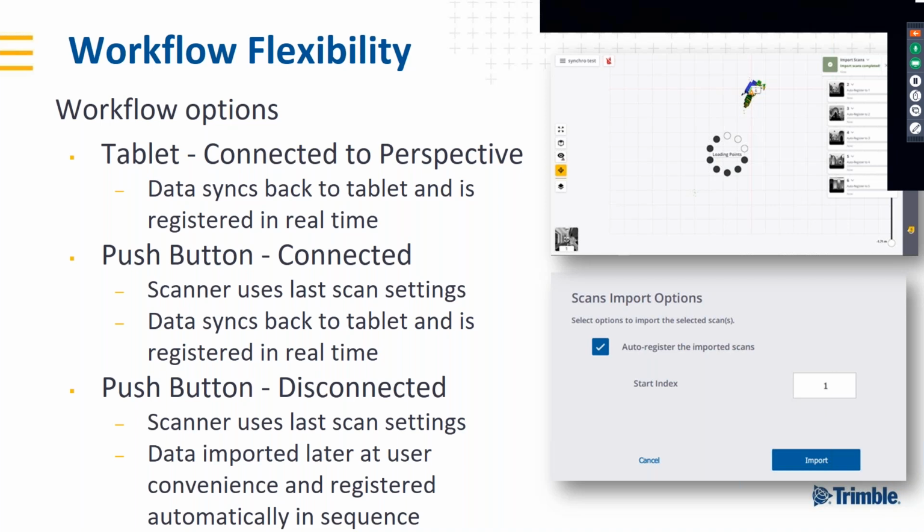Push button is slightly different, but let's say you're operating in a big area or small area, whatever it is, and you're not carrying the tablet. You simply lay the tablet down because the Wi-Fi connection is pretty good. You've just done a scan, your tablet lies on a bench or whatever, and you move that scanner maybe 15 meters away from where the tablet is. So rather than having to walk all the way back and press the button, you can just give it a push on the side of the scanner, and it will initiate the scanning inside the perspective software too, so that it can just go on.